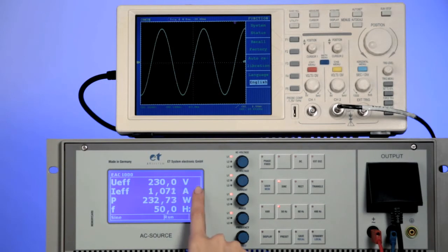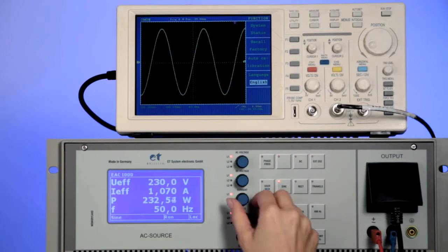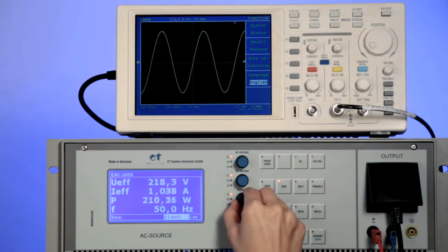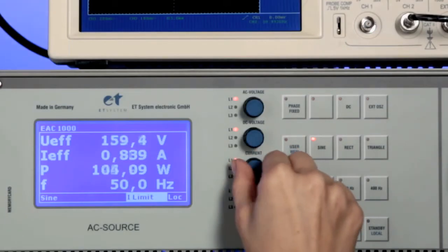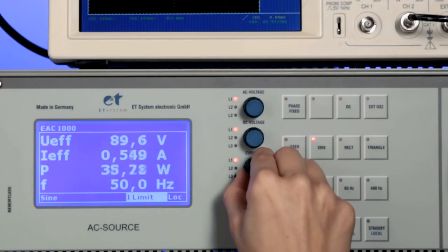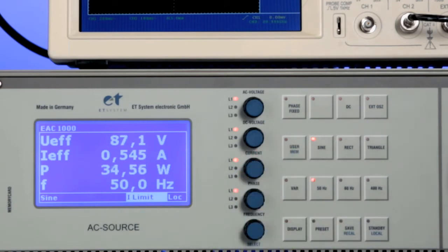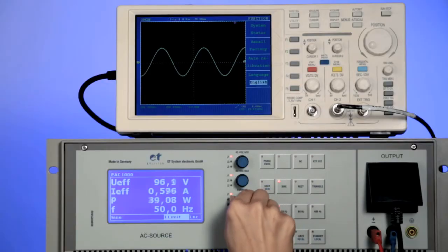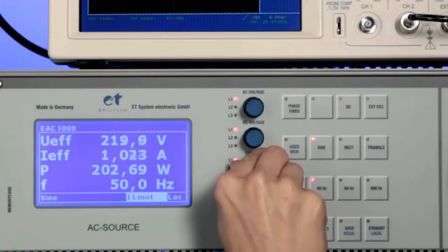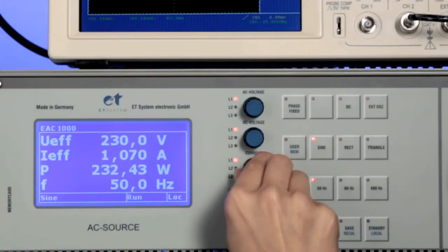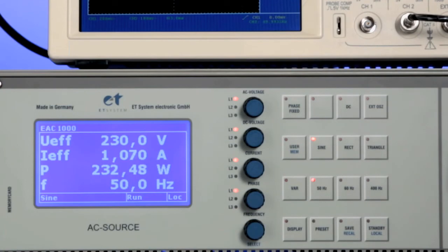In addition to the preset voltage, you now see the actual current flowing through the specimen or consumer. Now turn the current controller to the maximum current under the actual value, and you see that the device is switched to the I-limit mode and the voltage comes down accordingly to remain constant at the value set. If you increase the current appropriately, you can disable the current limit again and the unit returns to normal voltage mode.